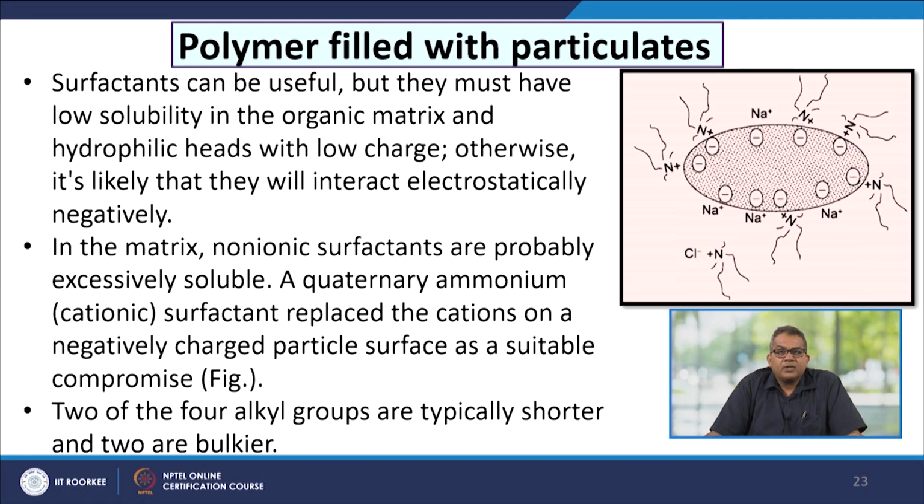The surfactants can be useful, but they must have a low solubility in the organic matrix and a hydrophilic head with a low charge. Otherwise, it is likely that they will interact electrostatically and negatively in the matrix. Non-ionic surfactants are probably excessively soluble. A quaternary ammonium cation surfactant replacing the cation on a negatively charged particle surface is a suitable compromise.